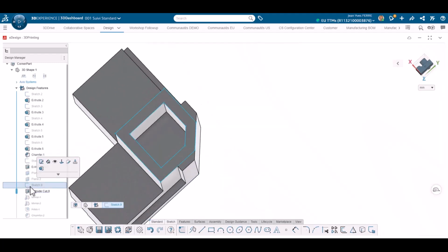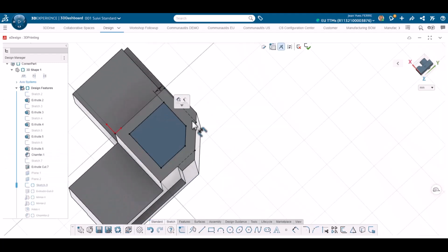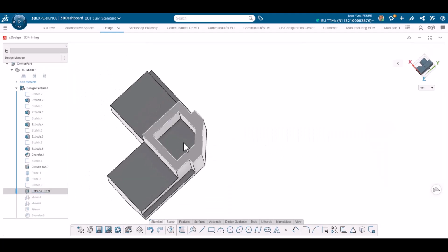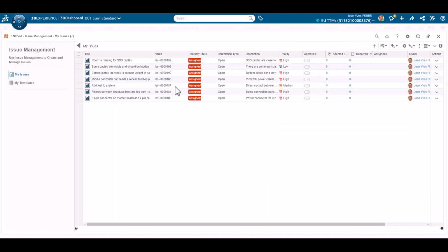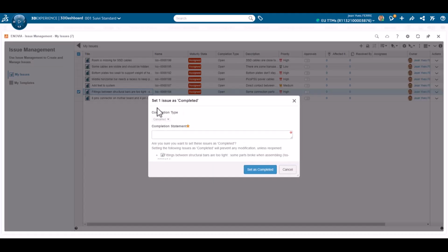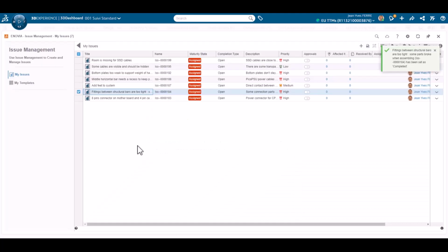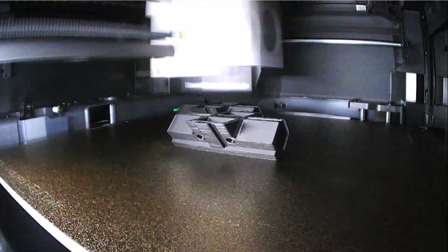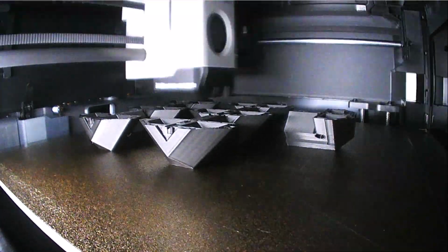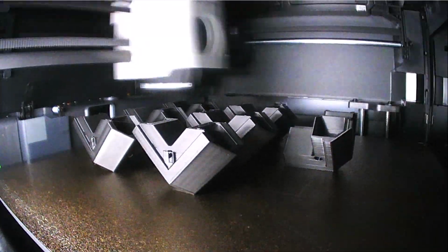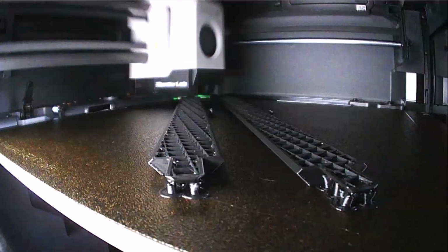Okay, let's change all fittings to a rounded dimension, for female fittings 14 or 16 millimeters, and an offset dimension for male fittings 13.8 or 15.8 millimeters. Remember, you need a clearance of 0.1 millimeters on each side of a 3D printed fitting when printing PLA in FDM. Once I have added how I solved the problem in Issue Management for future reference, it's now time to 3D print new fitting parts, corners and crosses, then new bars when needed.